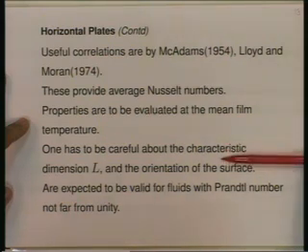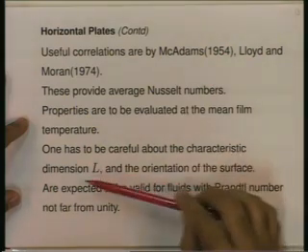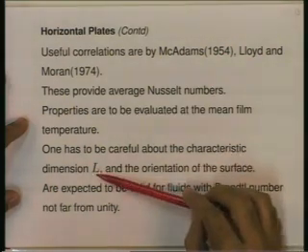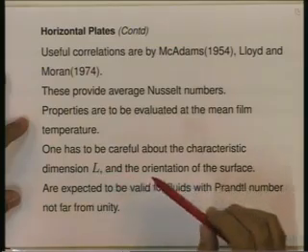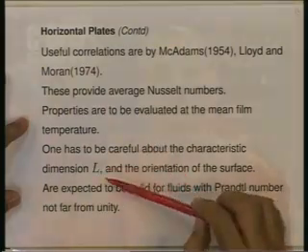One has to be careful about the characteristic dimension used in the dimensionless Grashof number or Rayleigh number, because the definition of L differs for each shape of the plate, and it also depends on whether the plate is facing upwards or facing downwards.